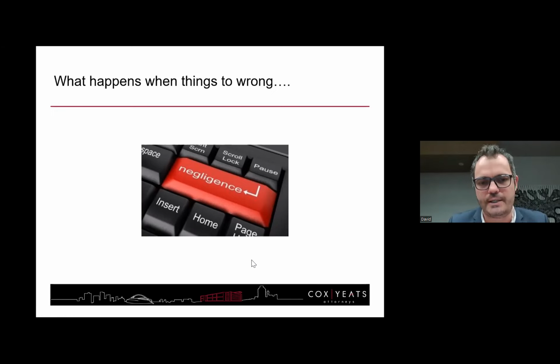Every single contract will stipulate a different term on liability and set different liability parameters. So that's the short answer, is you've got to actually work out what the contract data says, what the adjustments or amendments are in the special conditions or Z clauses under NEC3 or particular conditions under FIDIC. You've got to get the contract data, strip it out, take a look, and actually see what it says. There is actually no one standard.